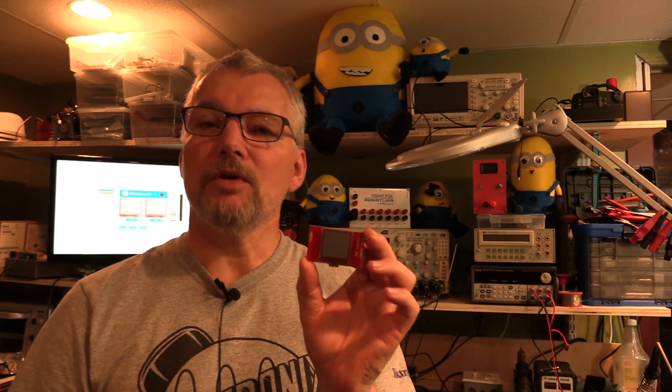It really depends on how much power you want to save. The more you do it, the more energy it will use, but you're only talking about a few microamps versus a couple of hundred microamps. I mean, in the scheme of things, it's not a lot. And compared to how much power the Pi is taking on its own when it's running anyway, it really is insignificant. So, I wouldn't worry about what speed you use. I just happened to pick 200 milliseconds just because it was a handy figure that wouldn't overload the performance of the machine or anything like that.